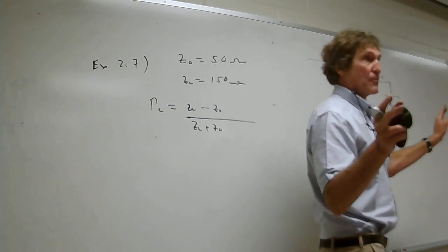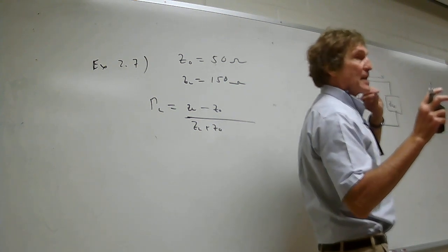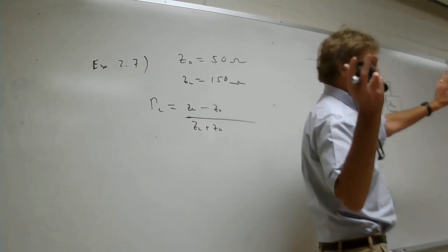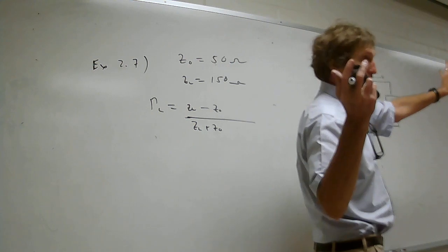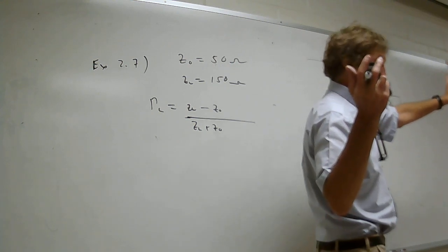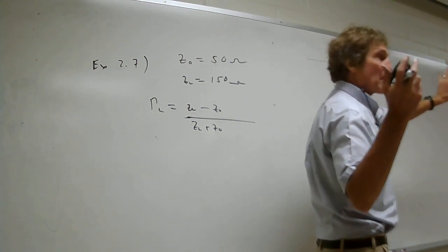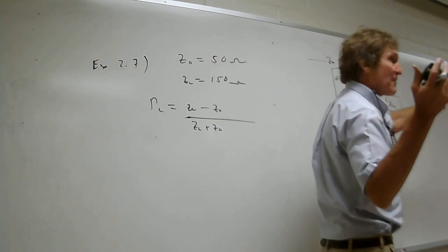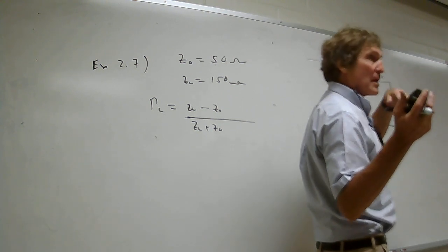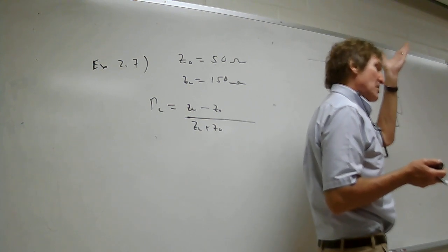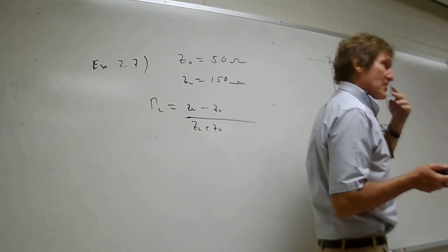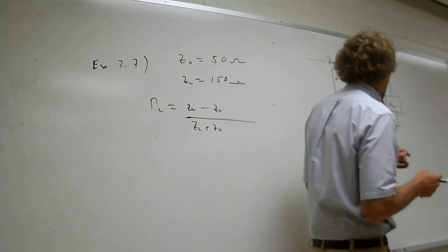That's what you strive for when you make any kind of network where you have an antenna with a power supply or a power amplifier. You want everything launched from that antenna. It has to be impedance matched. It's true in general with any circuit. You don't want stuff bouncing back and forth because you can get all sorts of voltage accumulation, and that will cause all sorts of problems. You got that? So anytime you're communicating, that would be ideal.